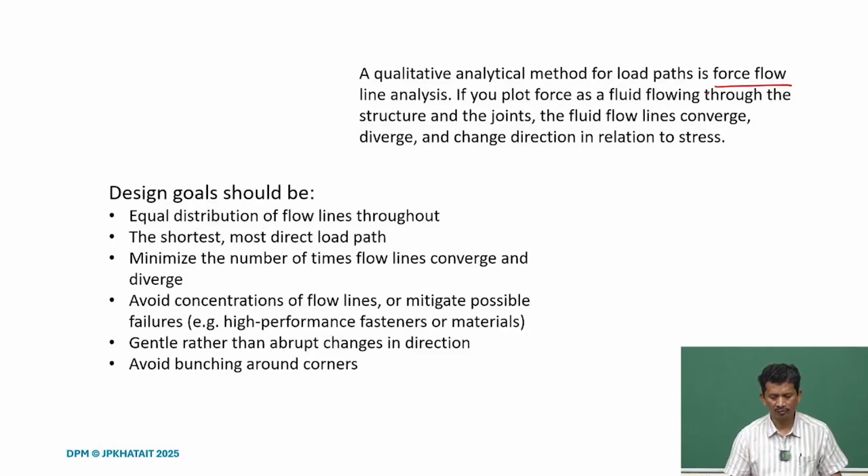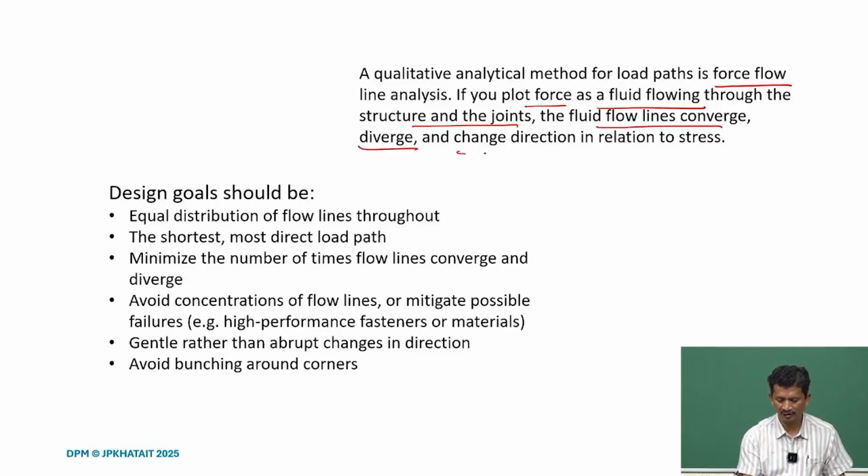If we are able to visualize that, and if we plot force as fluid flowing through the structure and the joints, what we see is that these fluid lines converge, diverge, even change directions, and that will help us to visualize if there is any kind of stress concentration and the nature of the forces, the loads, and then we do the calculation accordingly.